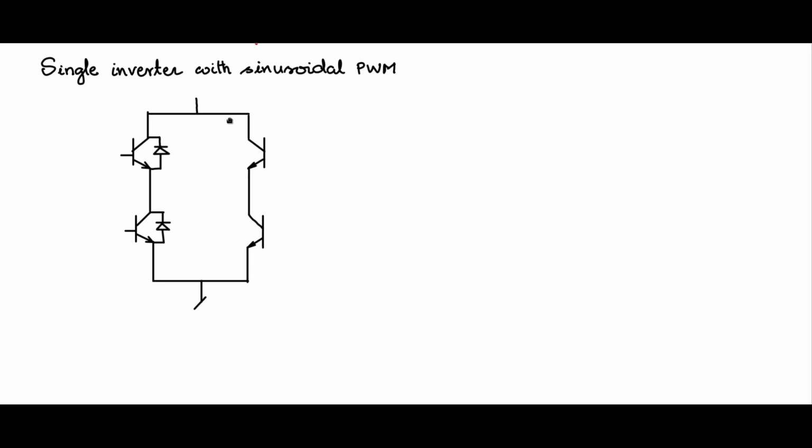So you also put another arm just like this arm. So you have another set of BJTs, a top BJT and a bottom switch, in this fashion. This is VCC, this is ground. Let us call this Q1, this Q2, this Q3, and this Q4. In between here we will have the load. So we will have an RL load, let us say L and R. So this is our full bridge converter.